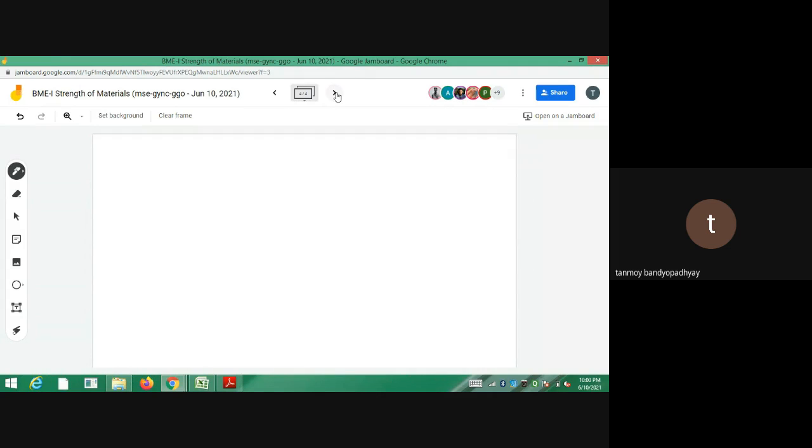Now the moment of inertia of the entire figure. So now we have got IG1, IG2. So the MI of the entire thing, I mean the rectangle plus rectangle plus semicircle, I'm writing it as IG about the centroidal axis of the composite shape, which is passing through G. So the axis now is x0, y.